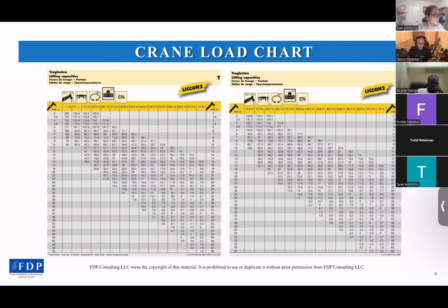So before you start to have a look at the crane table, make sure you have all the information of the crane that you're going to use, like the counterweight configuration, radius, boom configuration, and whether there is any jib attached to the boom. What is the type of the hook, if the manufacturer gives multiple hook options, and is the crane allowed to slew, and anything else?